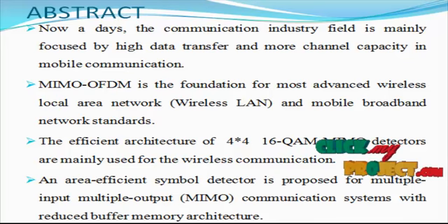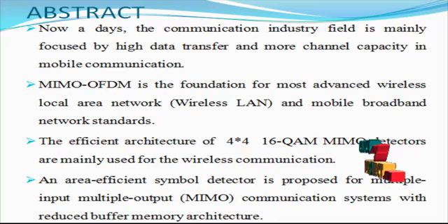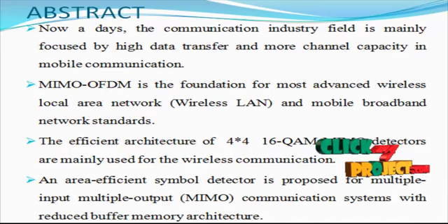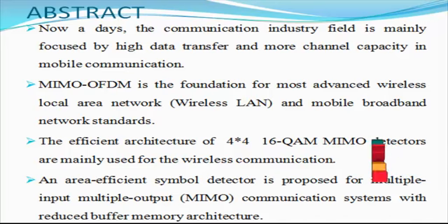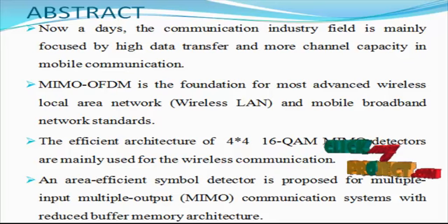This is due to the fact that the transmitted data is mixed together because of the extra DFT block used in the SC-FDMA system. Therefore, the implementation of a low complexity MIMO detector is needed, and it is a main challenge in the SC-FDMA framework.